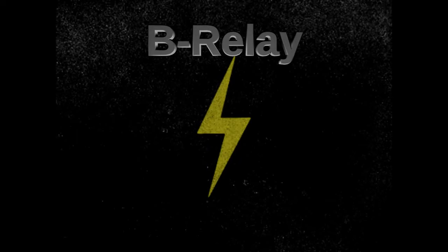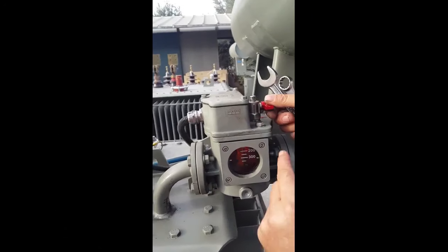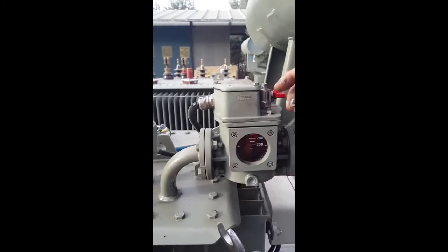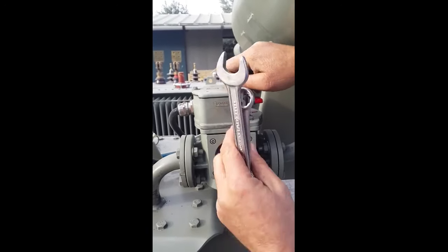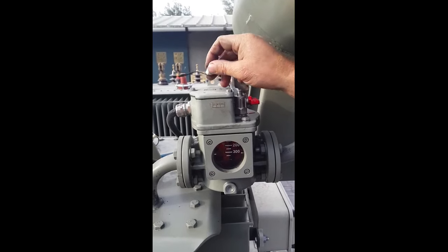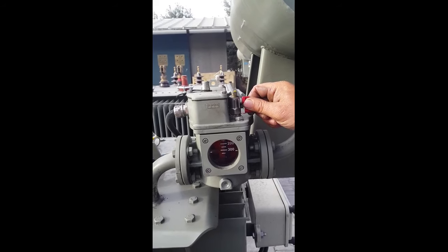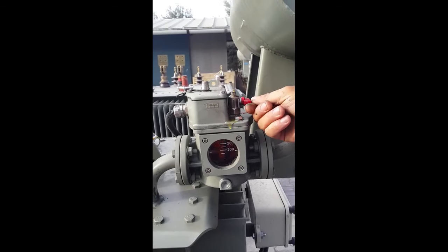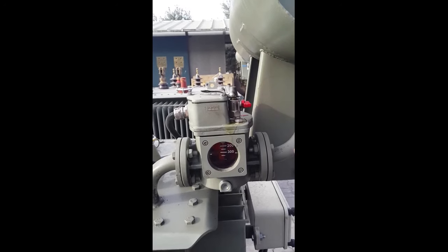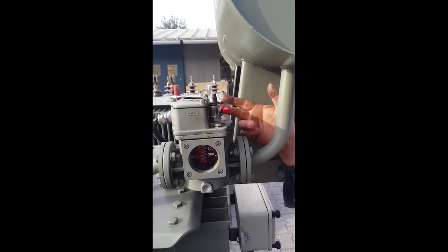Buchholz relay. It is a protective relay of the transformer. This device signals the fault as soon as it occurs and cuts the transformer out of the circuit immediately. The piping between the main tank and the conservator is arranged so that any gas involved in the main tank tends to flow upward toward the conservator and the gas detector relay. So as you can see, the Buchholz relay is connected between the conservator tank and the main tank.